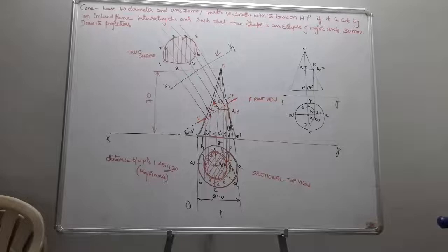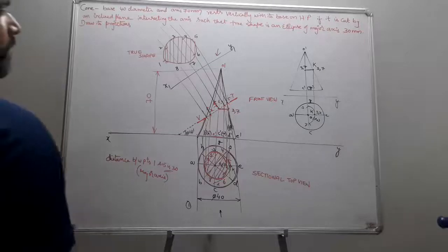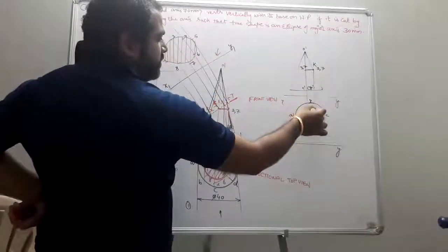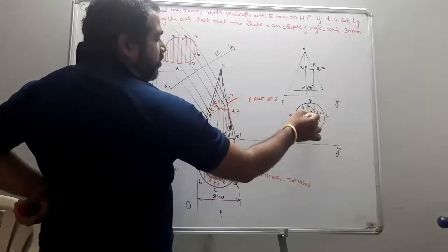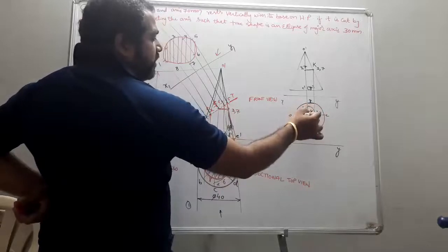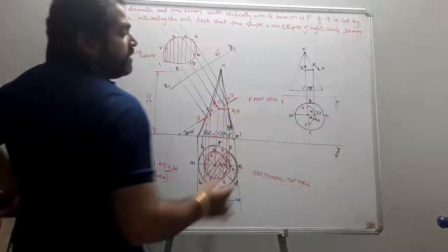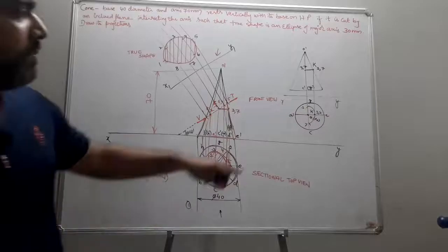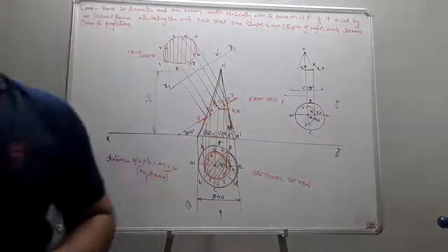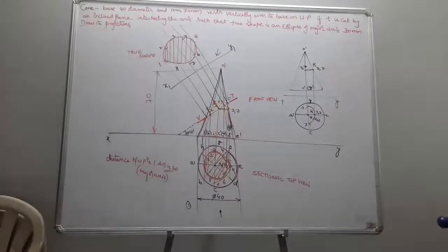I just transfer my points 3 comma 7 to the true slant edge. Here OE and OA are the two slant edges. So I project my points to the true slant edge, and from there I project it to the top view, it comes to here. Now with O as center and this radius, draw an arc. That becomes your 3 comma 7. Okay, students, is it clear?